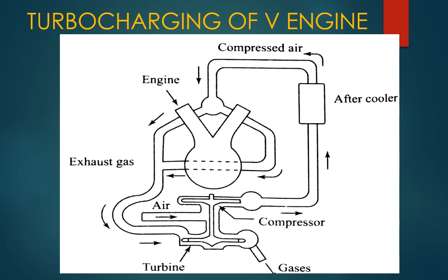What is the need for an intercooler? We have to increase the density of the air. When I increase the density of the air, obviously the temperature also increases. The increased temperature would sacrifice the increment in the density of the air. So I have to reduce the temperature so that I get compressed air which has higher density. This high density air is passed into the engine to produce more output from the engine.